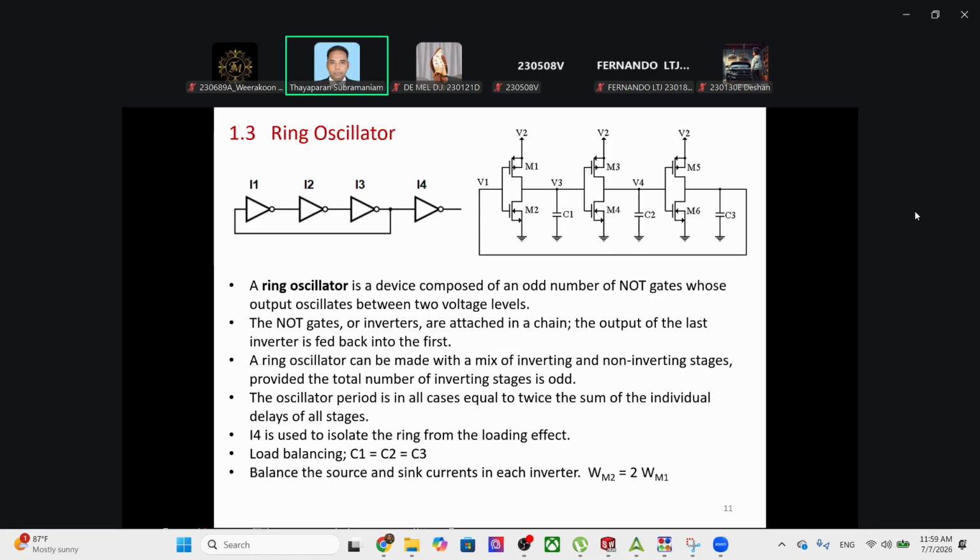If you plot the eye diagram, what you have to do is trigger at the positive edge and plot it in the middle. So you will see sometimes the positive edge goes to the left side, right side. The width of the zero crossing, that is the middle point of the logic 0 and logic 1, or high and low, is how much time it deviates compared to the period of the clock. So plus or minus how many percent?